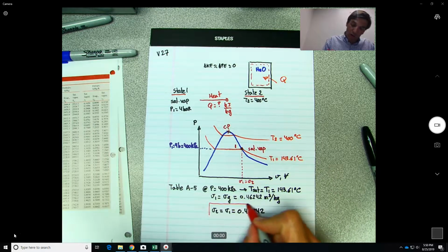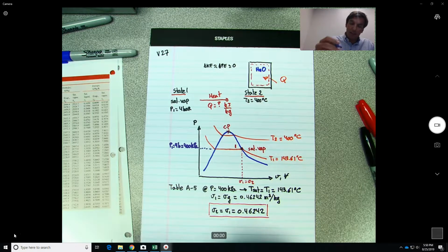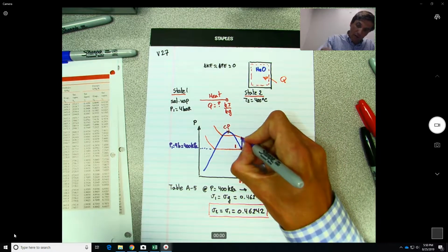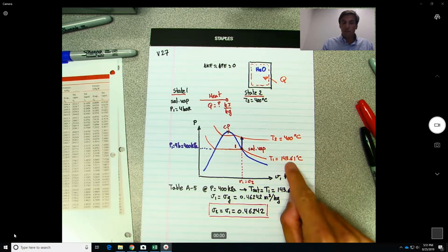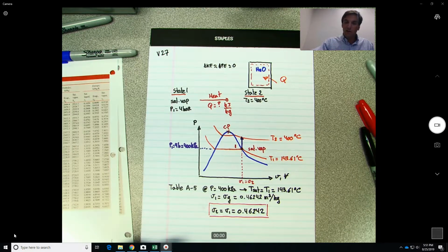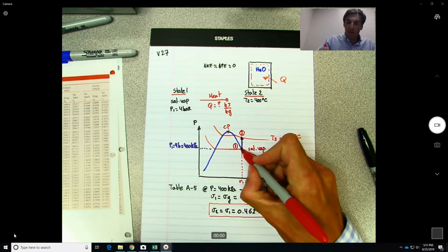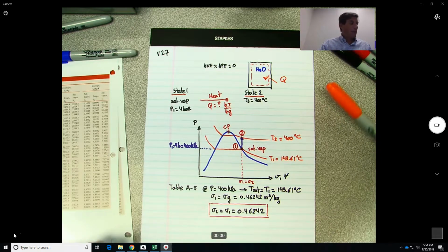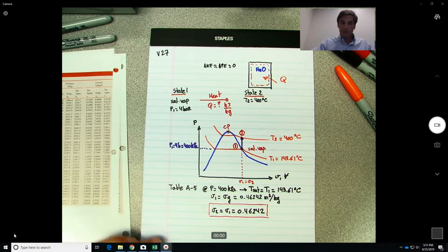So that's also important, because what that is telling us is that the process will be going through this line of constant volume. So we go from this line of 143.61 to this line over here of 400, and this will be state 2. So from state 1 saturated vapor to state 2. Okay, so this should be like steps 0 and 1 on the procedure.